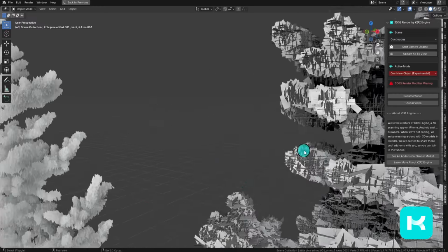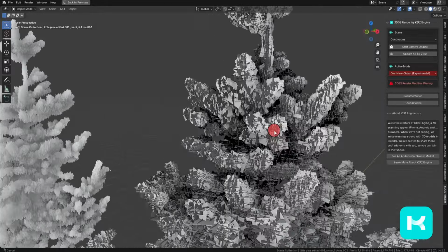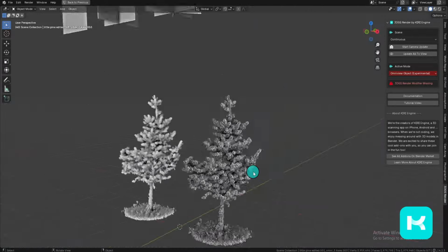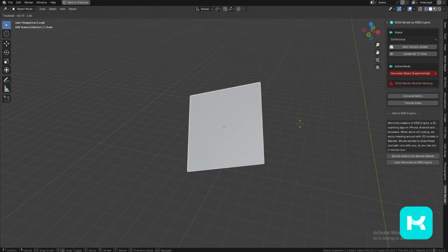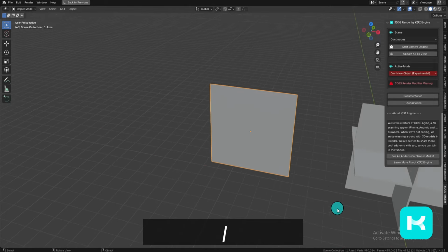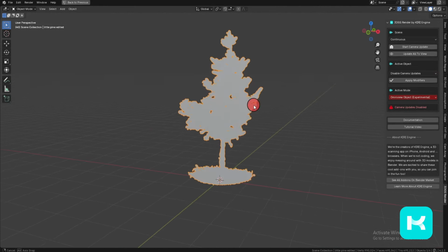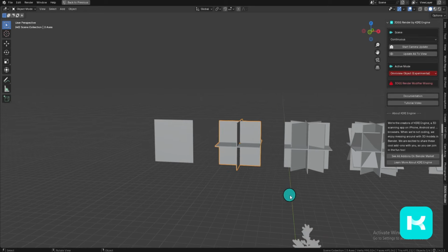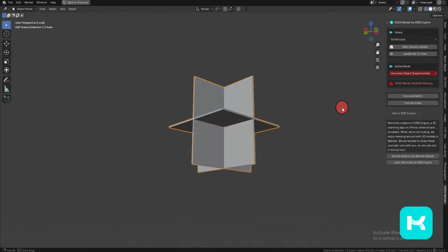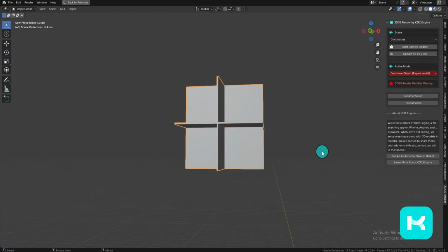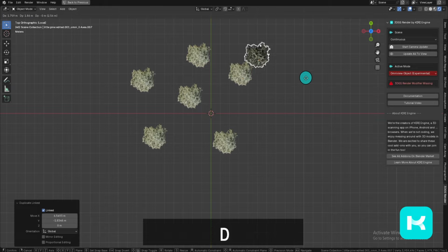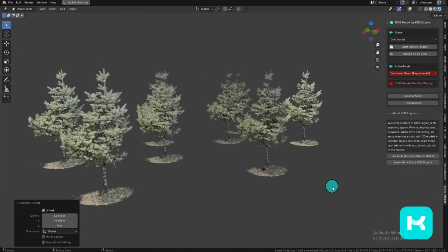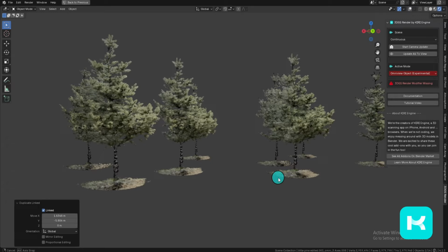Omniview Object. If you are familiar with the concept of imposters in video games, this is a similar experimental approach. The standard 3D objects have one face per 3D point, and this face rotates to the current view. An Omniview object has multiple faces per point. Each face is static, does not rotate, and faces permanently aligned to a specific axis. These objects don't need updating and can be instanced, making some performance-heavy tasks much lighter.